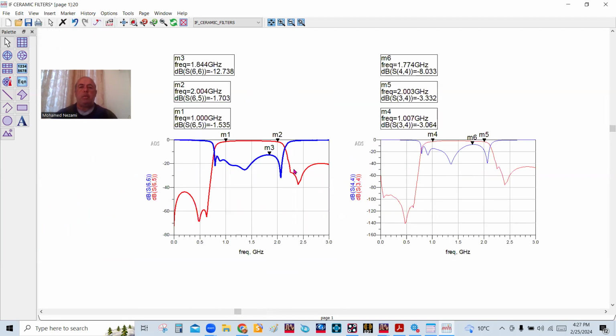And now we can see as a comparison, when we cascade 2 75 ohm systems together, of course, the insertion loss is doubled, which is correct on both sides. And the return loss has deteriorated by around this much. It went down from minus 13 dB to about minus 8.